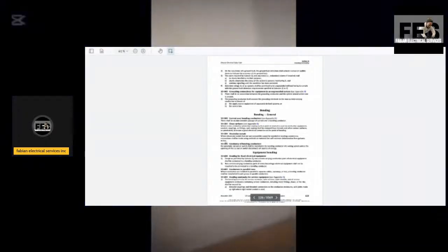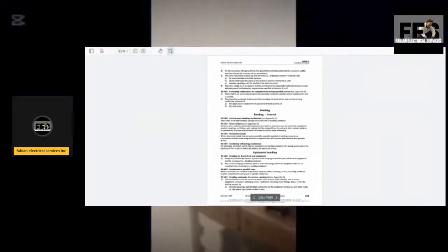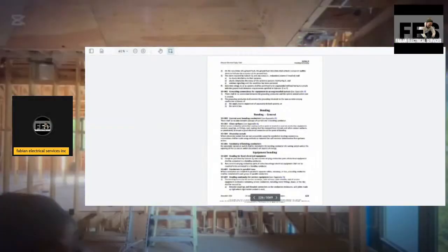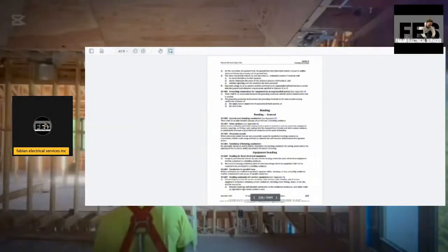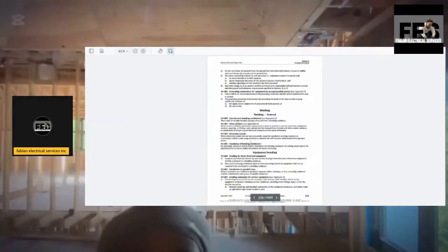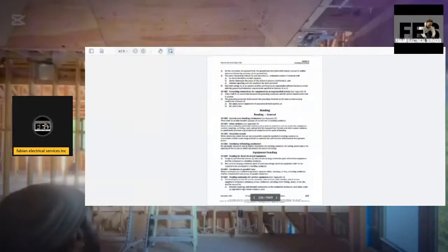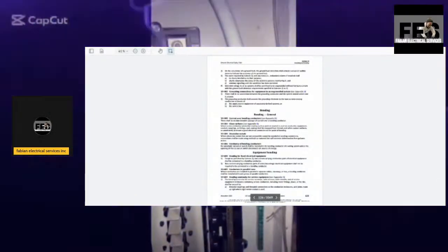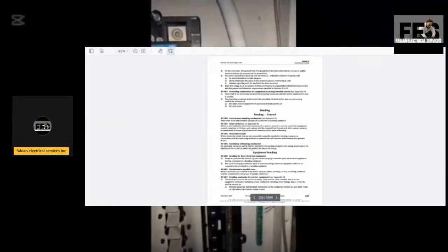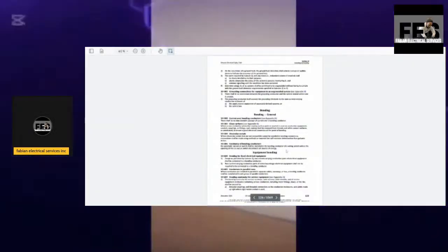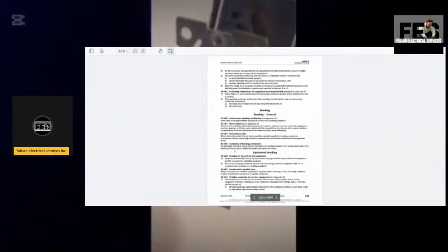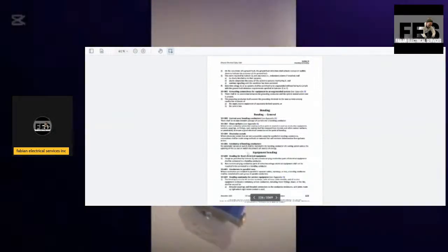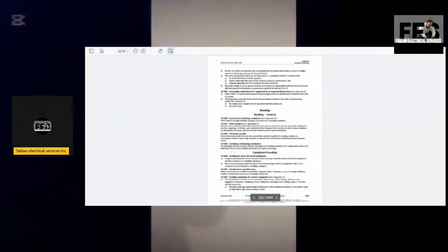Where dissimilar metals that are not compatible cannot be avoided at bonding connections, connections shall be made using metals or materials that will minimize deterioration from galvanic action. Continuity of bonding conductors: no automatic cut-off switch shall be installed in the bonding conductor of a wiring system unless the opening of the cutout or switch disconnects all sources of energy.